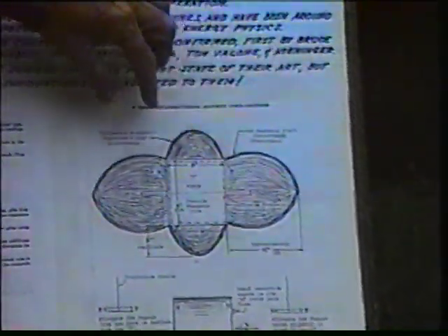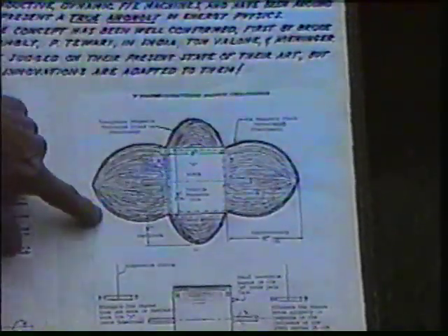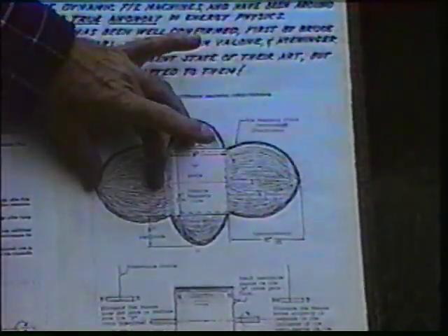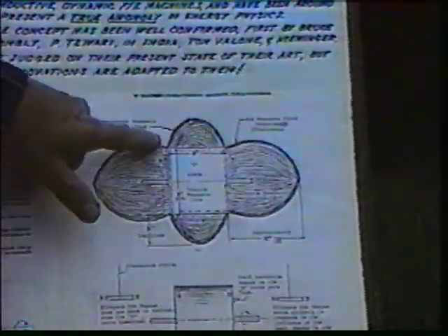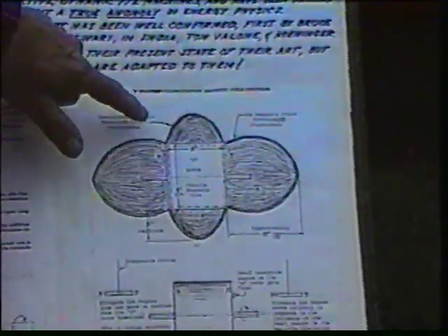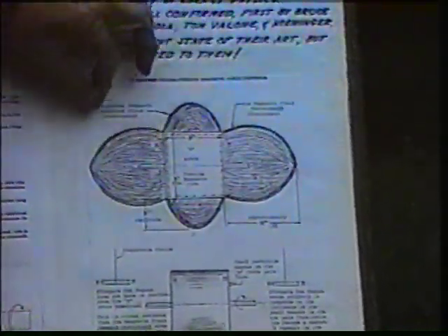That is a requirement. Now, a very interesting thing about this magnetic flux. You'll notice because of the use of these very powerful neodymium magnets, we get a very enlarged flux pattern. Each pattern is actually longer than the rotor itself, and it bows out somewhat. And also, you have the peripheral flux pattern. Or you can use a little magnetic detector. What you see here is pretty much to scale. So this is the pattern that you get.